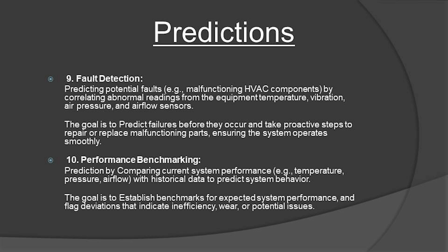Performance benchmarking: prediction by comparing current system performance, like temperature, pressure, and airflow, with historical data to predict system behavior. The goal is to establish benchmarks for expected system performance and flag deviations that indicate inefficiency, wear, or potential issues.